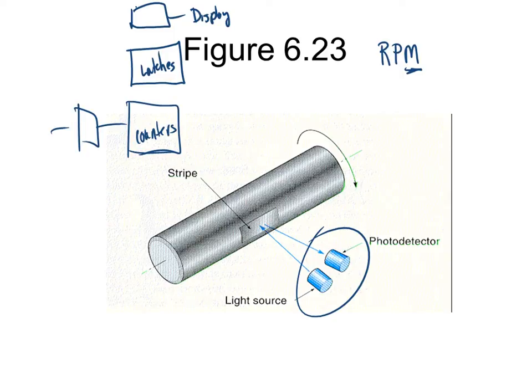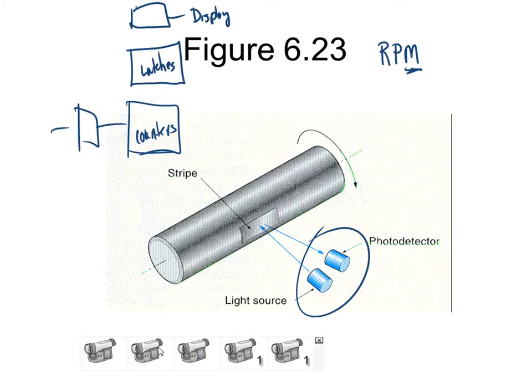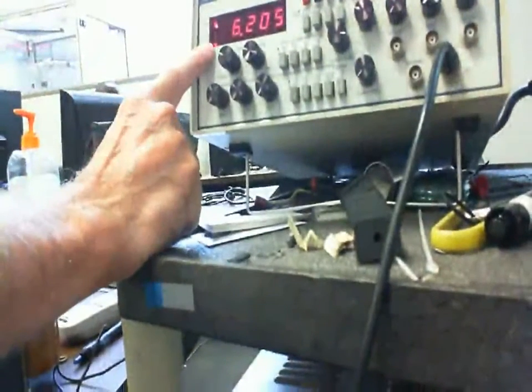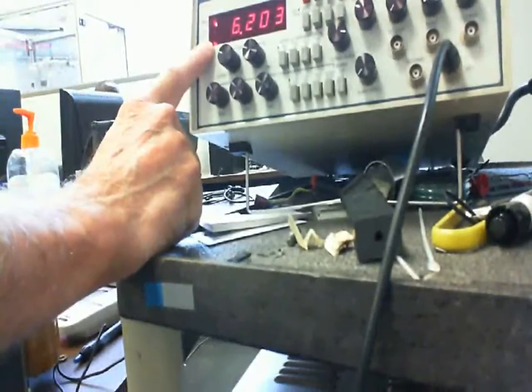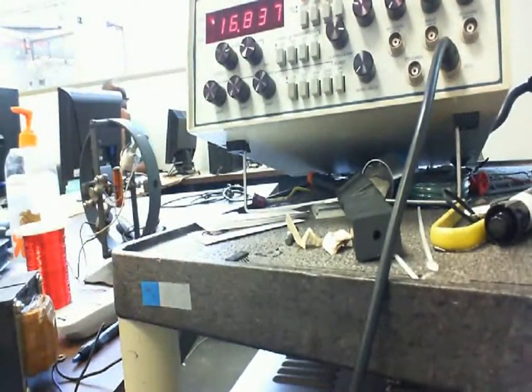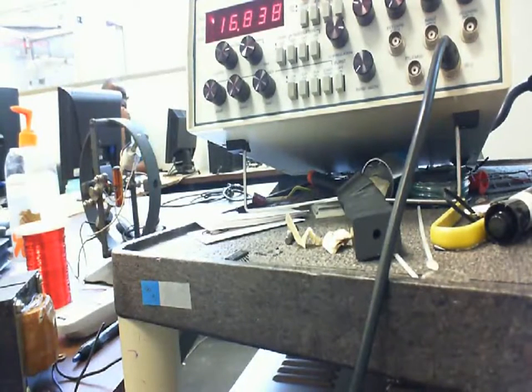We call it the gate, or how often we actually count. You can see it on a frequency counter really well because that's what they're doing. Over on the, which one was it? This one. So on my frequency counter, this little flashing light is how often it's updating the count. So you can see I can come over here and turn this knob, and it didn't move when I turned the knob. It waited till it did what?